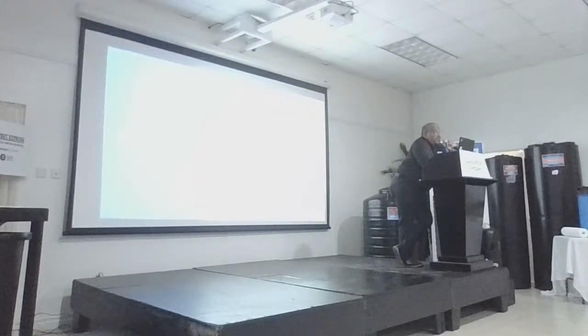And so the calculation is like 12,775 flushes in a year, which rounded out to about 35 gallons per person per day or per household. Right? So I went on the high end of 50 gallons. So even using 50 gallons a day, you're still doing more than the minimum retention time.